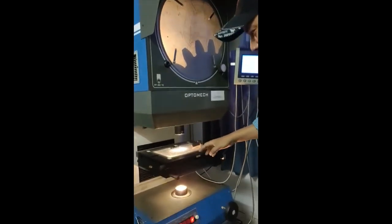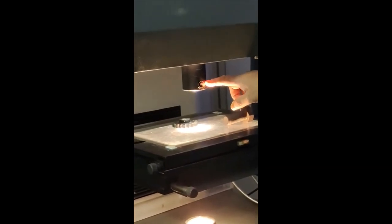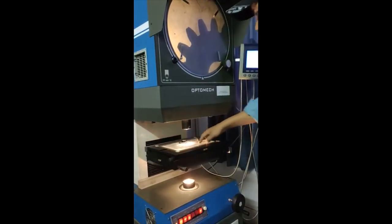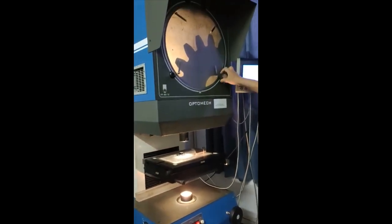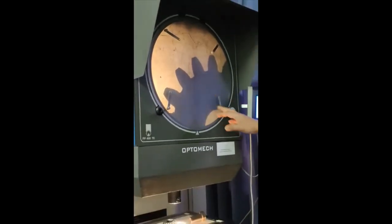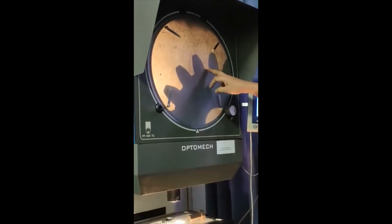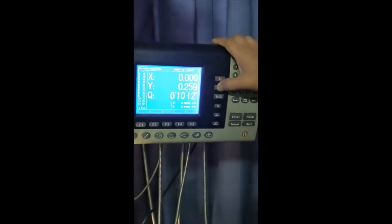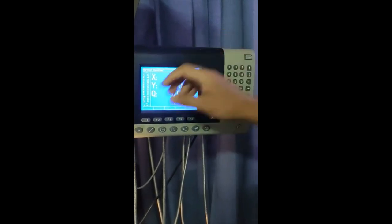This profile projector has a table and a lens. Now I am attaching a 10x lens, and whatever object you want to measure, suppose I am taking a gear, I will place this gear profile here. This gear profile will show on the screen. To read the profile value, we have a DRO, a digital readout, with a provision for zero setting.